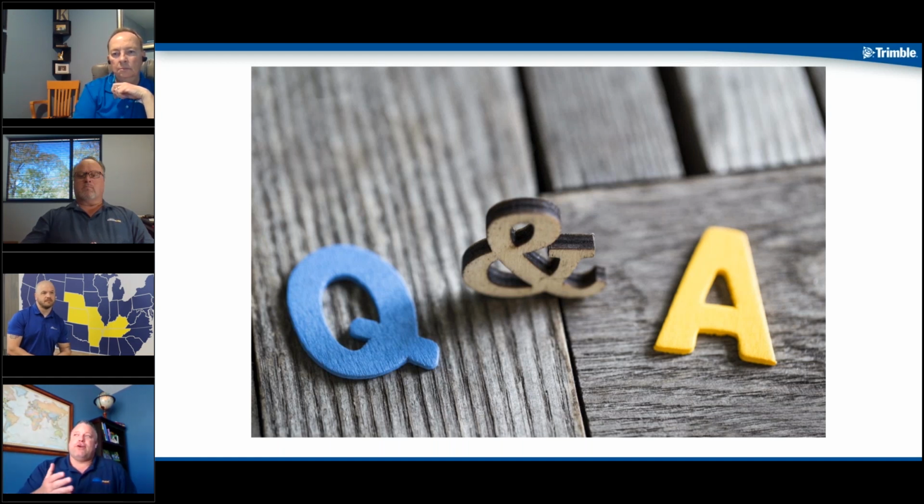And what in a surveyor's world would be is running a closed loop or running a traverse. And then at the end of that, you can run a network adjustment against that data to be able to confirm that what the traverse that you ran or the control points that you just shot in, to what degree of accuracy are they in. It's a least squares adjustment.